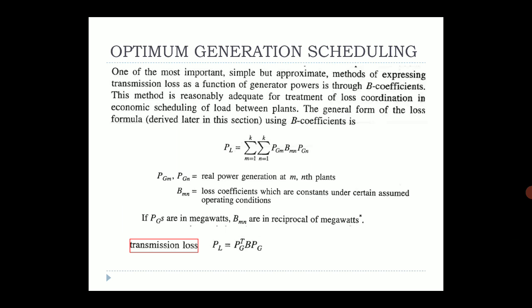So it tells you not all values of the B matrix are actually numbers. Most of them will be 0, because if one bus is not connected to the other bus, the B matrix element will be 0, just as in your Y bus system.